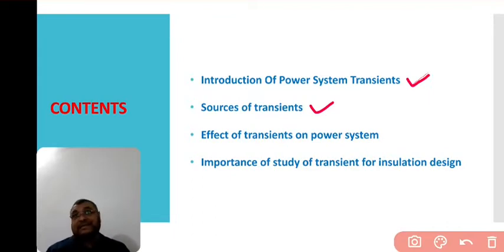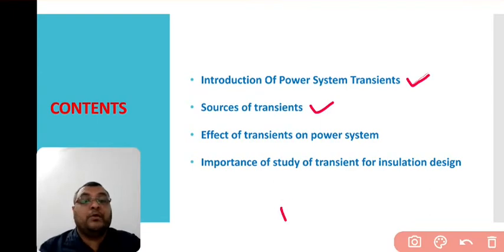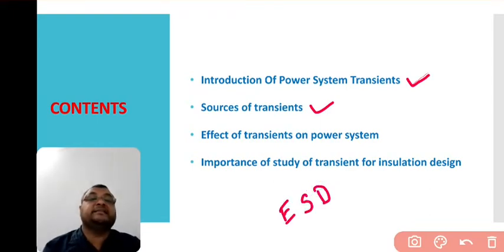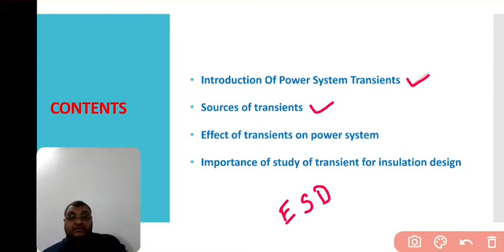Besides lightning, which is the main source, the internal causes include power electronic components, which are almost the major cause of transients. Then electrostatic discharge, also known as ESD. Other sources are copier and printer machines, welding loads, furnaces, ovens, induction heaters, etc. Also, you can consider motor load startup and turn off, faulty grounding connections, etc.